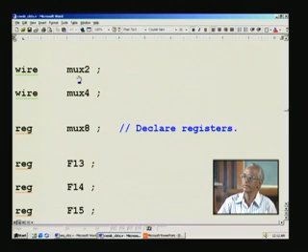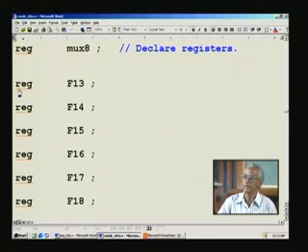And once again, you see, these are all where we did not use an always block, we used an assign statement for this. So we use a wire here, and we used an always block for the mux, therefore it is a reg, and these are all in always at positive edge. In sequential circuits, I think we have used this, that is why we have declared as reg.